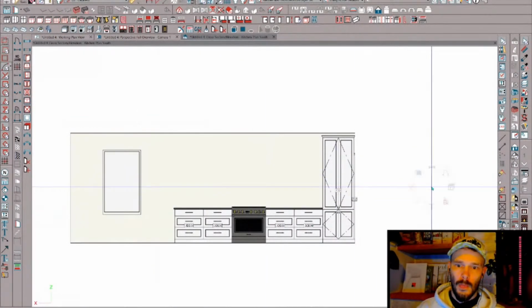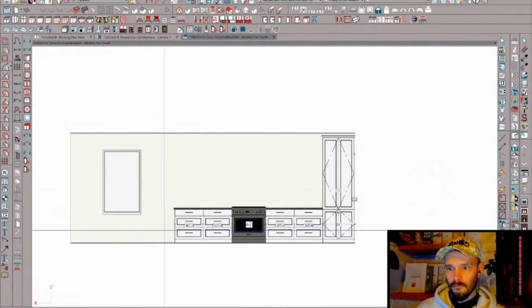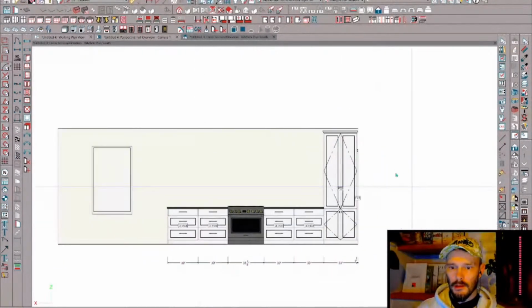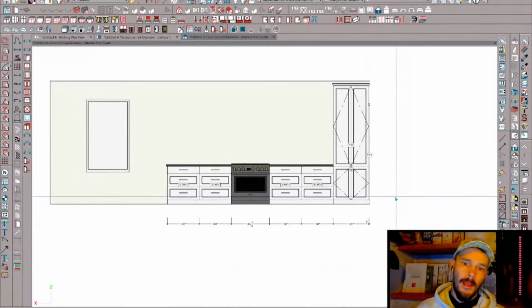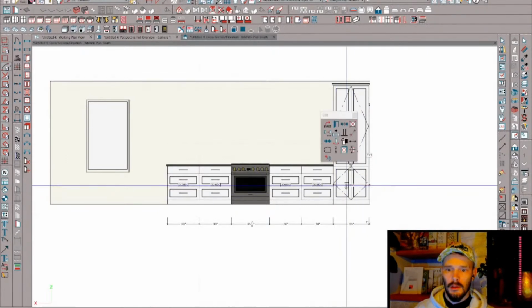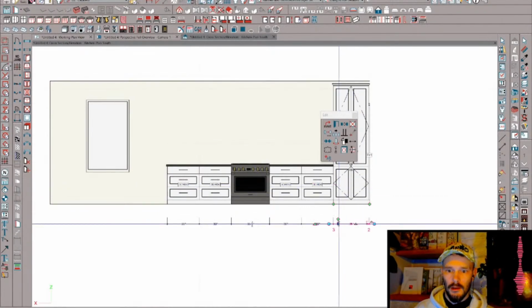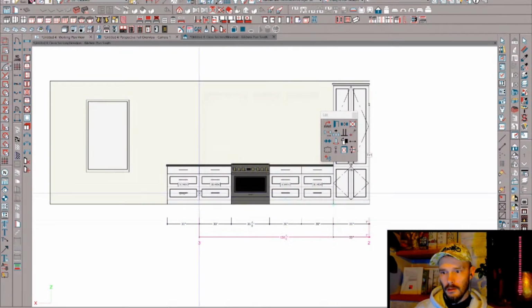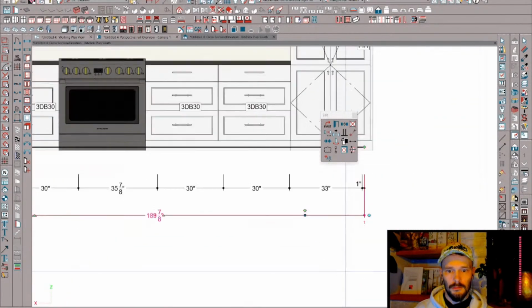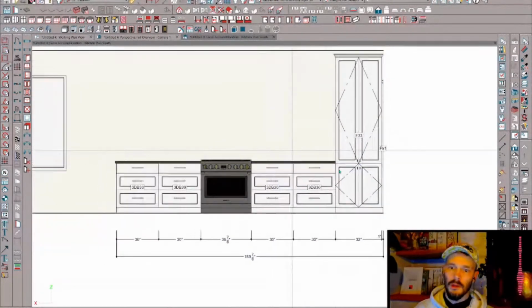Okay. I snap to there and then tab input 18 inches as my first run. That right there is my workflow. And then I'll bring this to there and tab that out maybe 12 inches. And we'll just make this the overall run. And pull this other diamond out. There's our overall run. That's pretty.